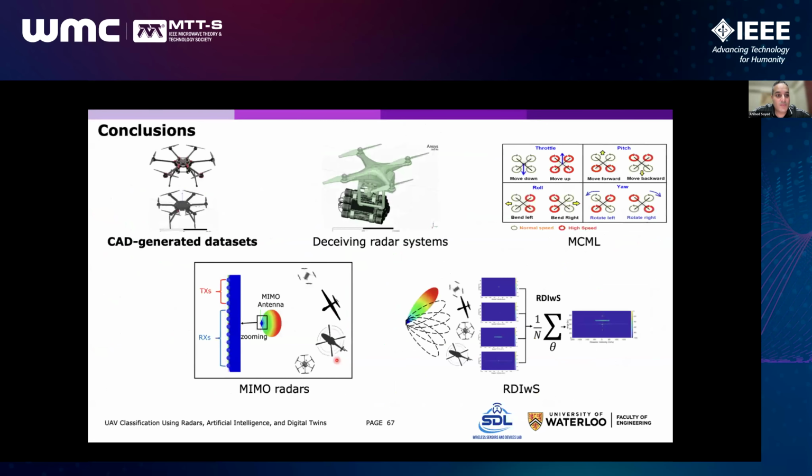Let's conclude our presentation. Full wave EM CAD tools can now be used for performing time-based full wave analysis. They can be used to generate a large number of complex data sets to be used in training machine learning models and developing signal processing techniques. Also, they can be used to investigate radar systems before they work in any application, not only in drone applications, before complex production campaigns. Also, attempts taken to deceive radar systems can be investigated using our proposed method.